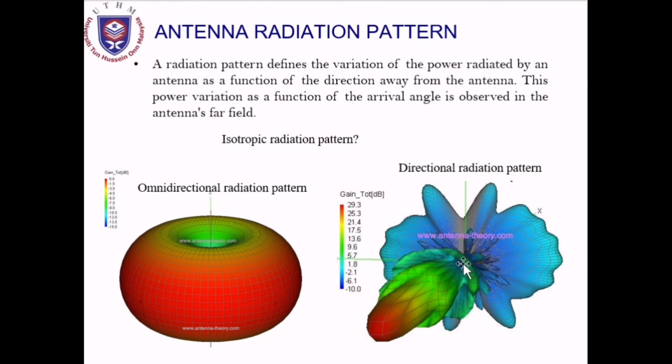Similar to the directional radiation pattern, this type of antenna has a single peak radiation in the radiation pattern, which is at the front over here. Usually the antenna with a directional radiation pattern is used for point-to-point communication. These antennas are very common. For example, high gain directional antennas include the parabolic antenna and also the slotted waveguide antenna. So it has a very directional radiation pattern.